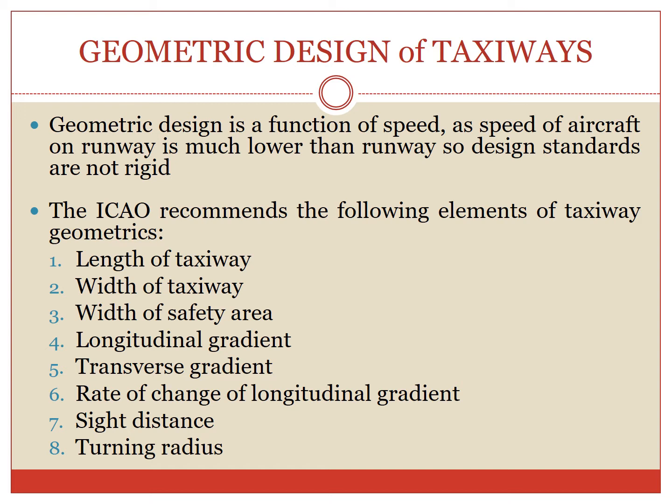These are the following elements of the taxiway geometrics: the length of the taxiway, width of the safety area, longitudinal gradient, transverse gradient, the rate of change of longitudinal gradient, the taxiway curves, side distances, the turning radii, and the stopping distances. These are some of the recommendations made by the International Civil Aviation Organization.